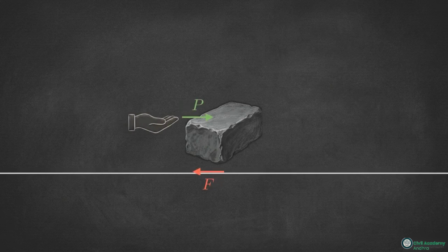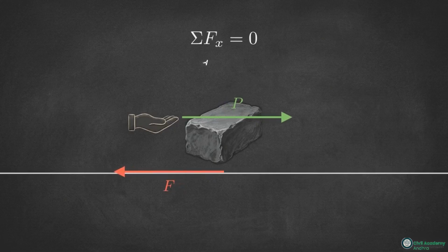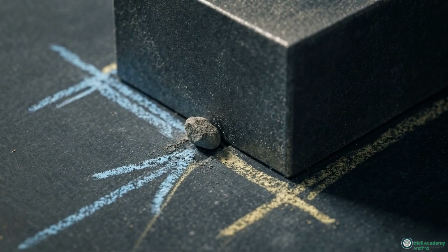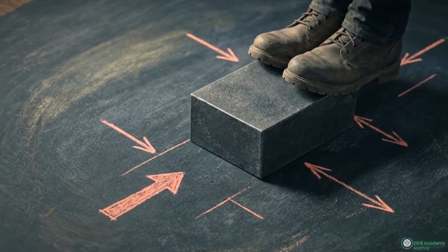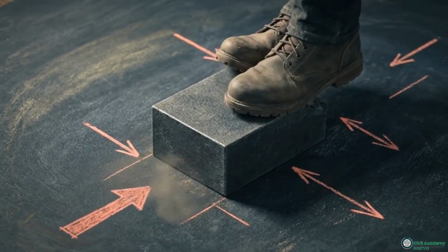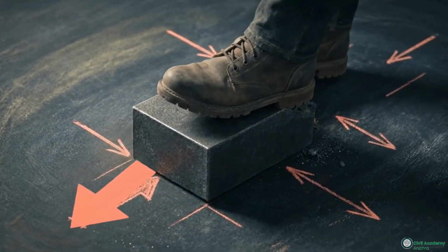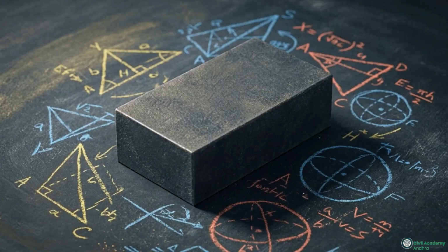This is a self-adjusting reactive force. As you push harder, the friction force increases to perfectly match your applied load, maintaining static equilibrium. There is a precise physical threshold where this equilibrium breaks. We call this limiting friction, the exact moment where the reactive force maxes out and relative motion is about to begin. Coulomb's laws dictate how this threshold behaves.